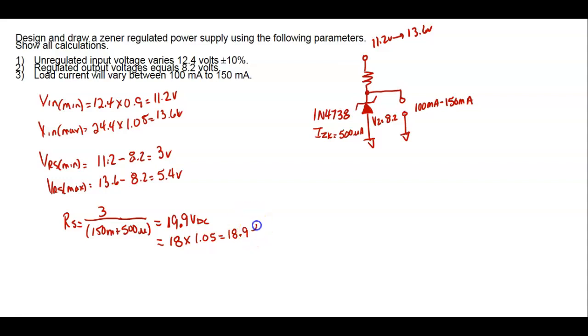What we're trying to do is see if this comes up to be greater than that. It's a check, because we want the Zener current to always go up. The problem is that the resistors we're choosing can be within 5%.